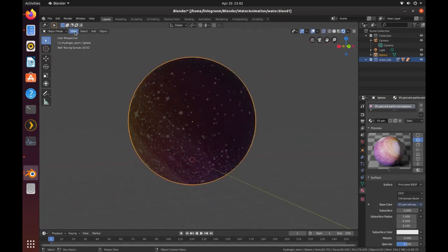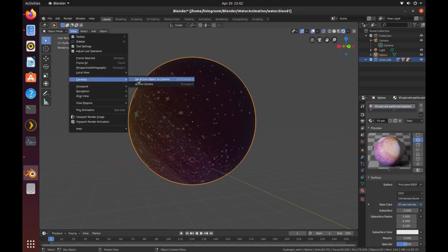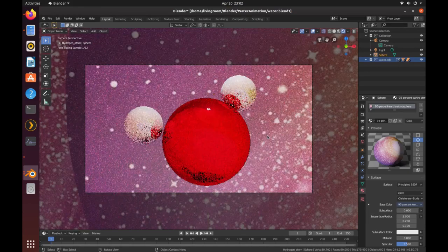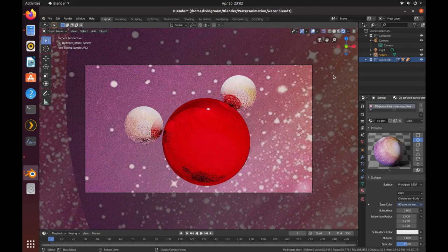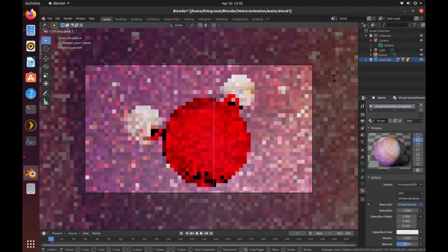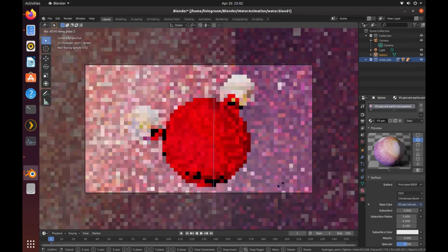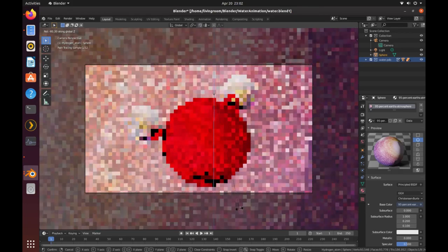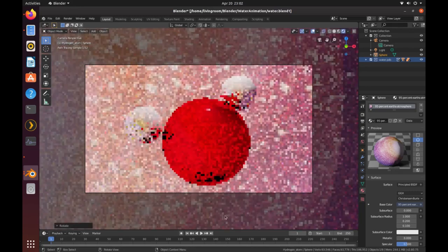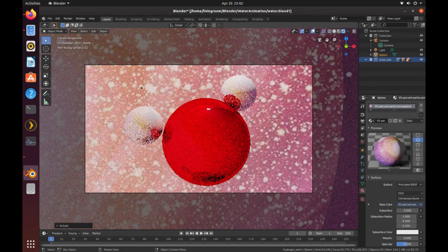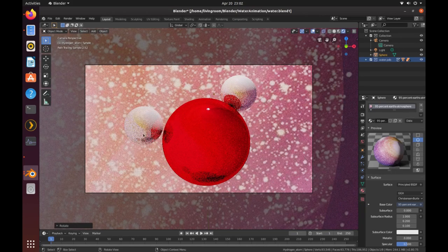So now I want to take a look at the scene itself by going to View, Cameras, and then Active Camera. And I want to select the UV sphere in the background, left click, and then type RZ, and I'm just going to rotate this UV sphere so I get a lot of the yellow colors in this left hand corner here. Great. So now we get a lot of highlighted yellow colors. We can see that the image is really reflecting off of the hydrogen atoms, and you can see there's some reflection through the oxygen atom itself.